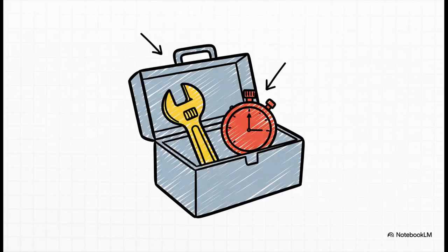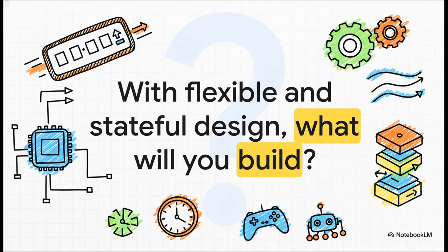So, let's wrap this up. We've just armed you with two of the most essential tools in the entire Verilog toolkit. You've got parameters for making your designs flexible and reusable, and you've got the always @(posedge clock) pattern, powered by non-blocking assignments for building circuits that have state and memory. By mastering just these two concepts, you have the foundational building blocks to design a massive range of digital systems, from simple state machines all the way up to sophisticated processors. The principles of flexible and stateful design are right at your fingertips. The possibilities are pretty much endless. So the only real question is, what are you going to build?